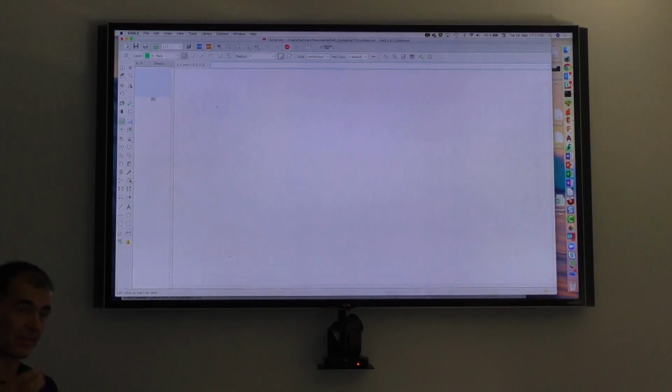That's what we have founded over the long story we have. In the beginning we all had commands. You activate the command and then you do it the classical way, or you do the right click. You could also execute all the commands in Eagle by typing them into the command line. If I want to draw a line, I type line, for example L-E, and it's automatically substituted to line, enter, and then I can draw a line. So this is also possible.